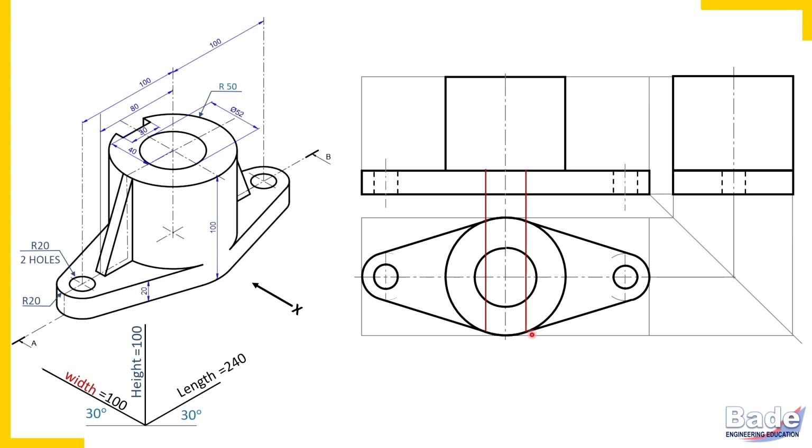I have drawn these projectors, these two red color projectors. Check here. This portion I have erased because it is a tangential joint here. And these two edges, watch here, this non-principal edge and this non-principal edge, meet the curved surface tangentially. So we'll use the proper notation to indicate the tangential joint. This is how we have created this joint.